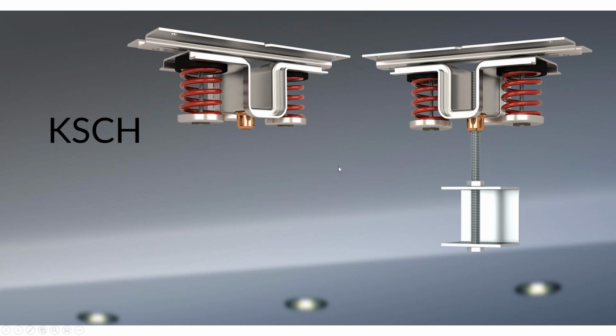And again, the other thing you can do is just drop straight threaded rod through there, down through your drywall ceiling, and then set up other grids to do your pipe, your duct, and other pieces of the kitchen sink ceilings, as we like to call them here.